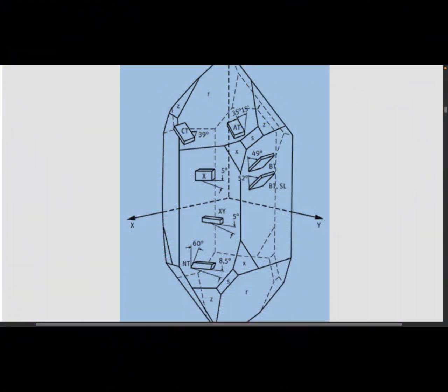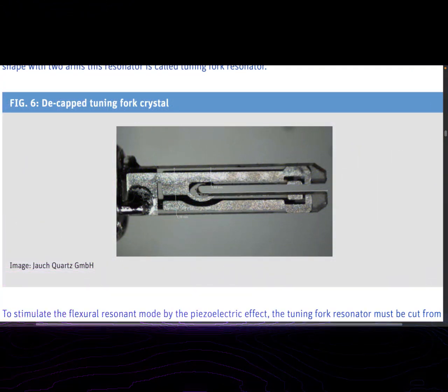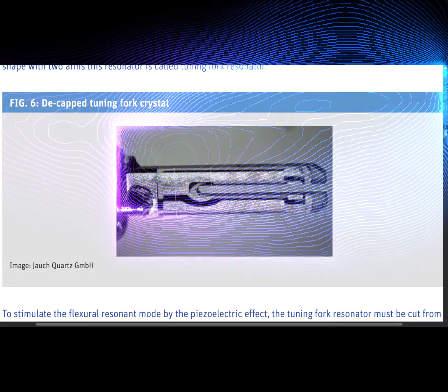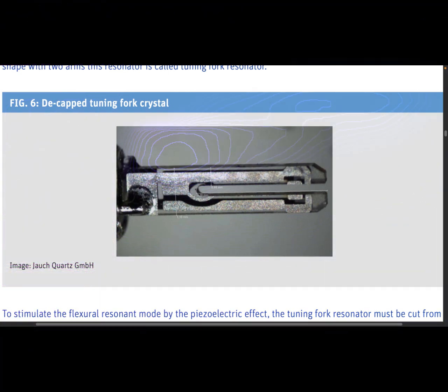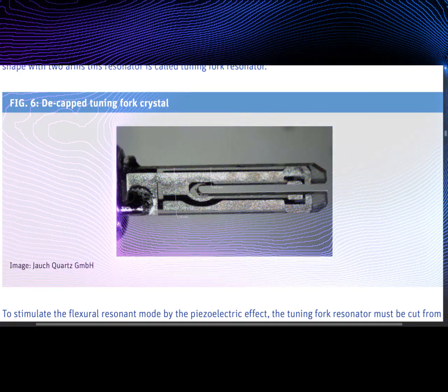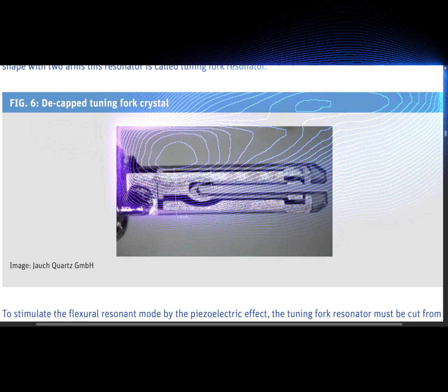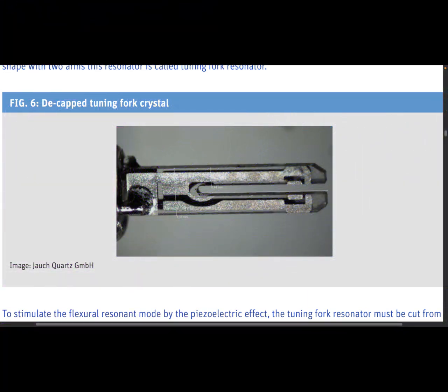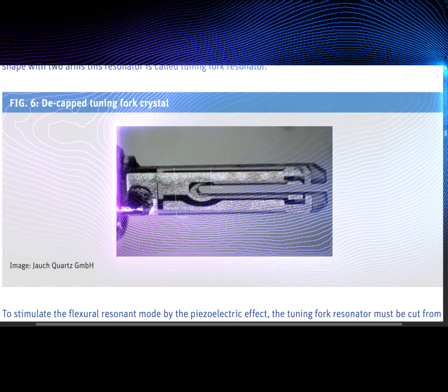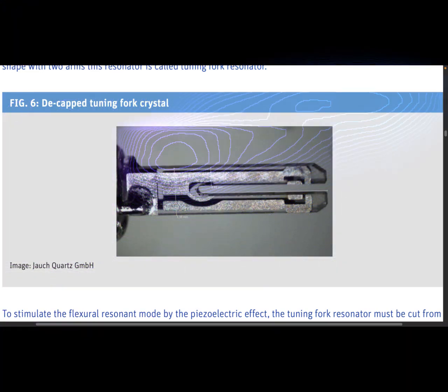The clock technology chosen also needs to balance system requirements such as cost and power consumption against technical demands such as frequency and stability. Types of clock circuit. One of the simplest types of oscillator uses a resistor-capacitor resonant circuit. More accurate oscillators can be constructed using ceramic or crystal resonators.